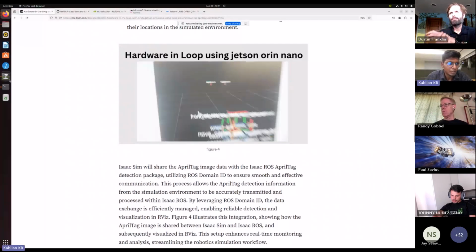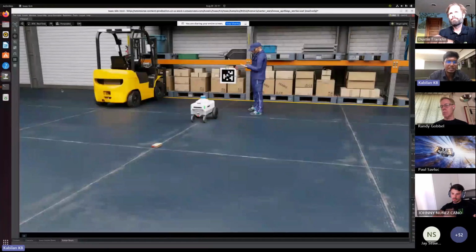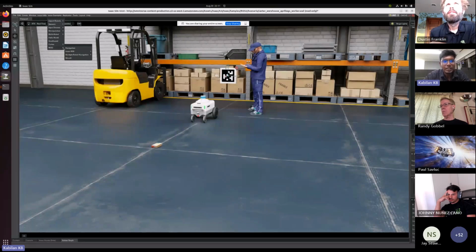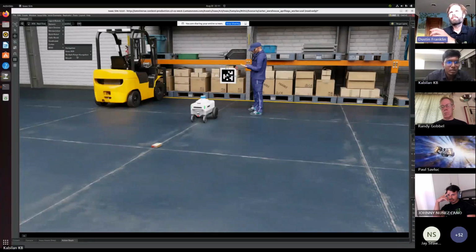Yeah. So in Isaac Sim they have already given the Isaac utilities and Isaac assets. So if you need to launch the Isaac Sim environment or the Isaac ROS testing environment, we have the Isaac examples. Here we need to go to ROS 2 and launch those examples, and we can try our hardware-in-the-loop testing or any of our own algorithm testing in the simulation part. Okay, so it just sets up the topics from there.